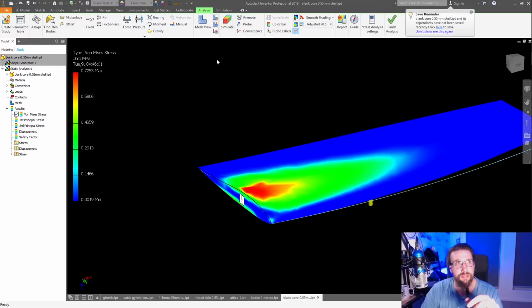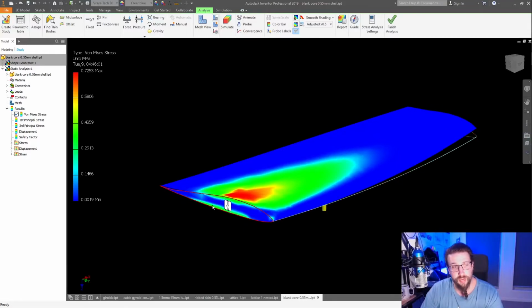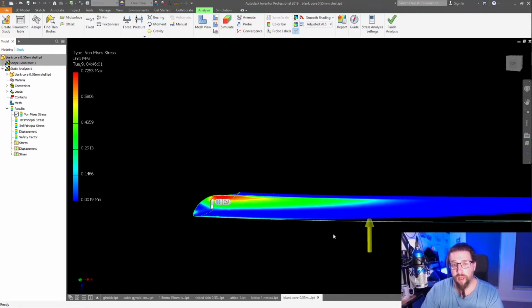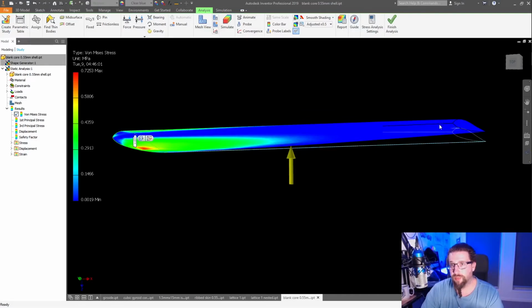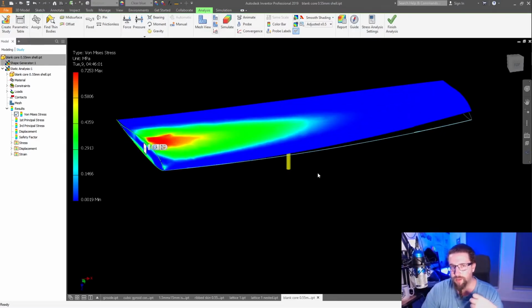Now, Inventor has a shape generating tool in it. So I can come in and say, okay, simulate the force properties. Now I just constrained this one face on the end here and applied a force over the entire top and bottom wing surface so that it's all distributed and equal. It's not the perfect way to do it, but it's pretty damn close.